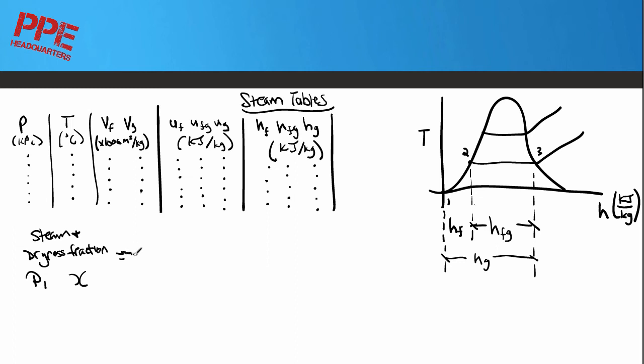So how do we represent that graphically? In that case, they really don't need to give us a bunch of information, and we can get where we want to be already, which is nice. With very little information, we know this is T, we know this is H. So we're told we'll draw in our constant pressure lines. And we are told that we are at some sort of percent dryness.